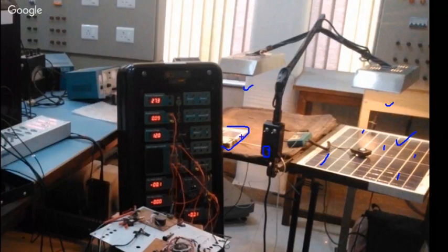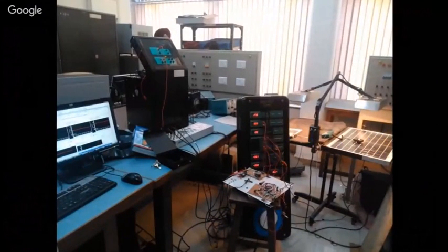So what we found is the output voltage of this panel for that 800. So we calibrated it. Now for 800, say some 8 volts is coming. We took that inside the computer and multiplied it by 100, and we told the computer that the irradiation is 800 watts per meter squared. Can you understand? So we have to calibrate it. We made our own irradiation sensor there, because we want everything in terms of voltage. Then we used an LM35 for measuring the temperature. So this was the irradiation sensor used.